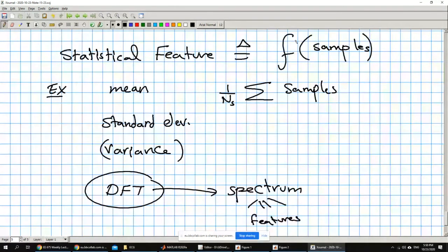You can think about it like, if you have ventricular fibrillation, for example, the high frequencies will be higher for ventricular fibrillation than for the normal. So you would expect them to be very useful as well. So the DFT, if you remember, if we have a 1080 sample vector and do DFT, FFT, whatever, you'll come up with 1080 values, right?